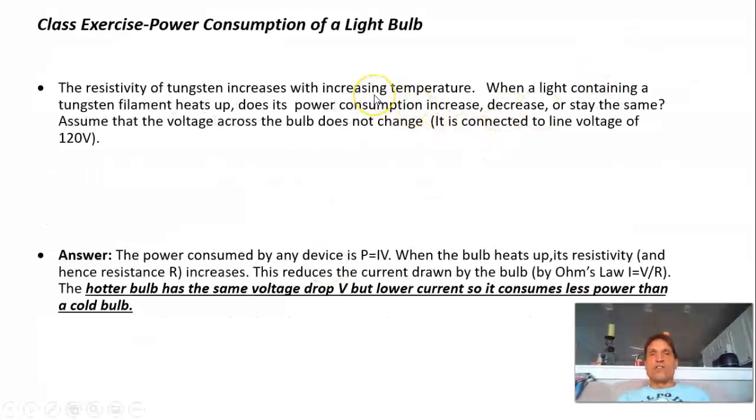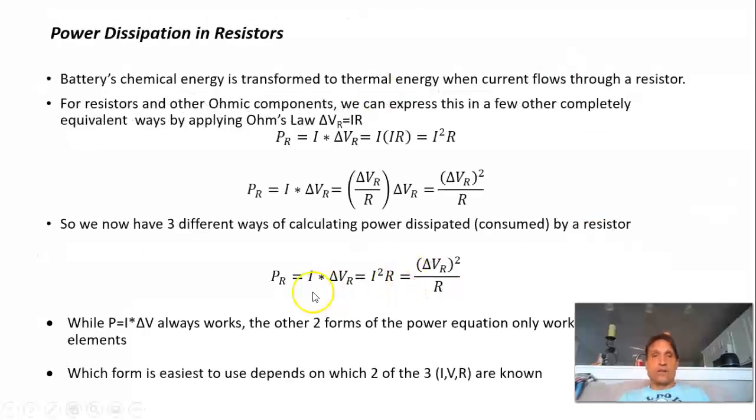Okay, and the resistance of the bulb is less. Resistance is less, current is more. So when you first turn on the bulb, lower resistance, higher current, higher power. As the bulb is on longer, the tungsten element gets hot, its resistance to current increases, which means current drops as the bulb warms up. Okay, current drops, power used drops.